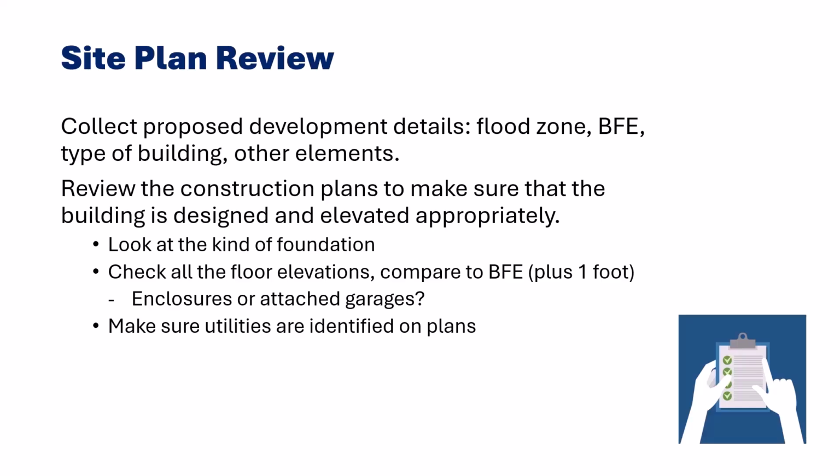As a tip, you can actually preload that flood insurance rate map information into Section B of the elevation certificate form. Review construction plan sets to make sure a building is designed and elevated appropriately. Look at the kind of foundation, check all the floors, and compare them to the base flood elevation or your design flood elevation of BFE plus 1 foot.